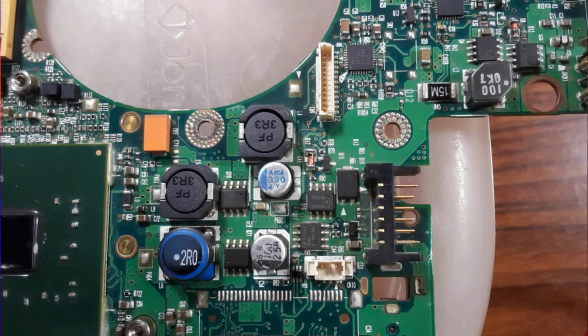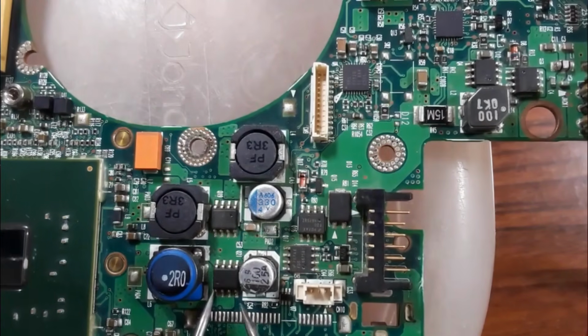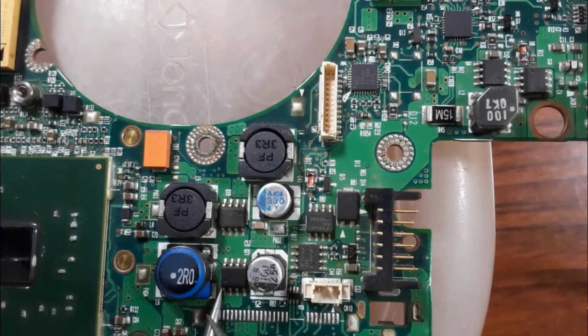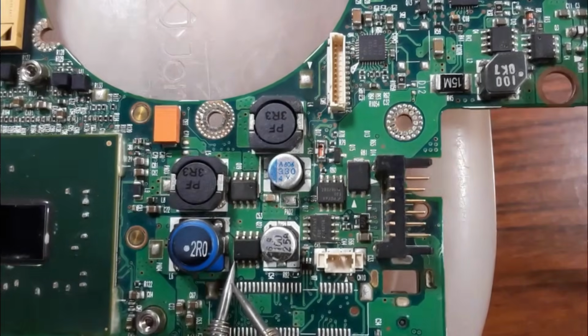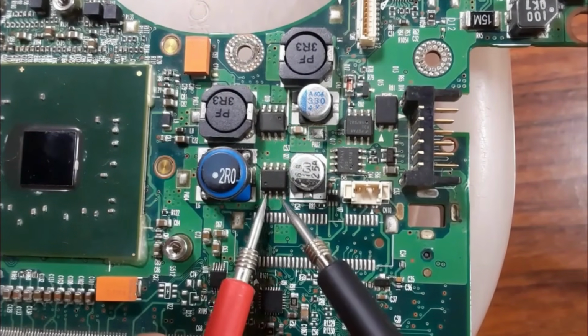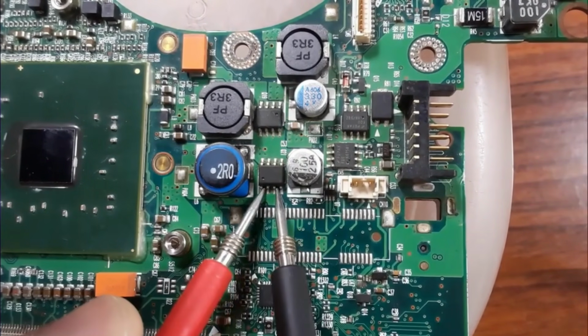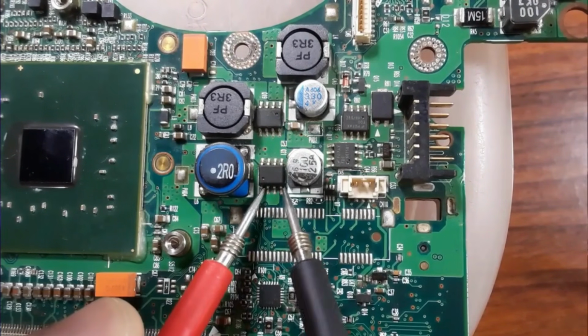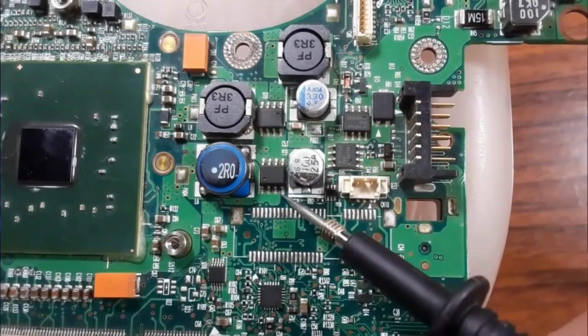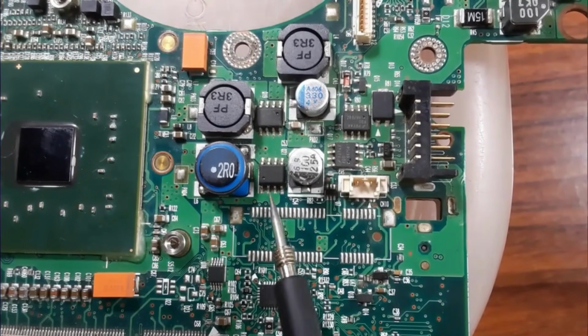So here we have a point, meaning this is source, these three are source. If we check these three, let's check the continuity first. These three are connected together, as you can see. And this also. Okay, this is the gate, of course. Do you see the gate? The gate is not connected with the source. Here we have a green color, here we have another color, here we have the same color, green. So these three are connected.